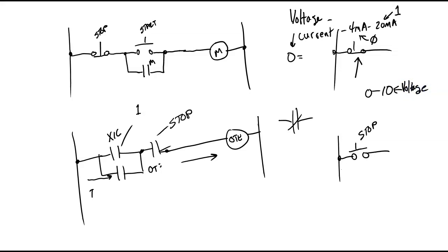I think on the Siemens that we have, you can set up the analog ports for the 314s we have. I think it's got two current loops and 3 voltage ports on their analog ports over there, if I think right. So there's a lot of things we can use besides voltage, and of course these are the two ways. We can't use resistance. Why? So normally we use either voltage or current to represent information going into the PLC, and this is also true for any computer.